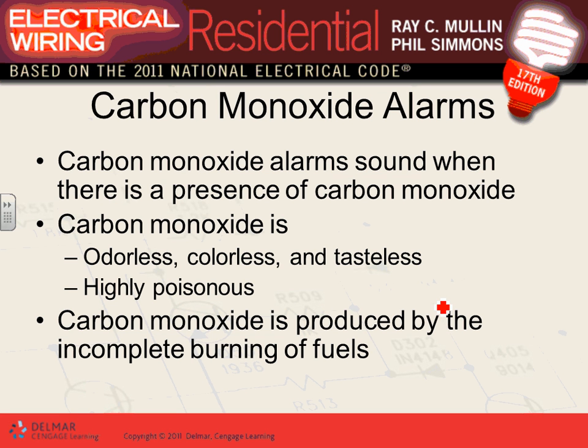Okay, carbon monoxide detector. Any comments about the smoke detector and the heat detector? Oh, by the way, heat detector, where do you need a heat detector? The code doesn't talk about heat detectors. The heat detector is typically needed in areas where a smoke detector will create nuisance alarms. Like kitchens, you put a smoke detector and you fry some bacon on a Sunday morning, what's going to happen?